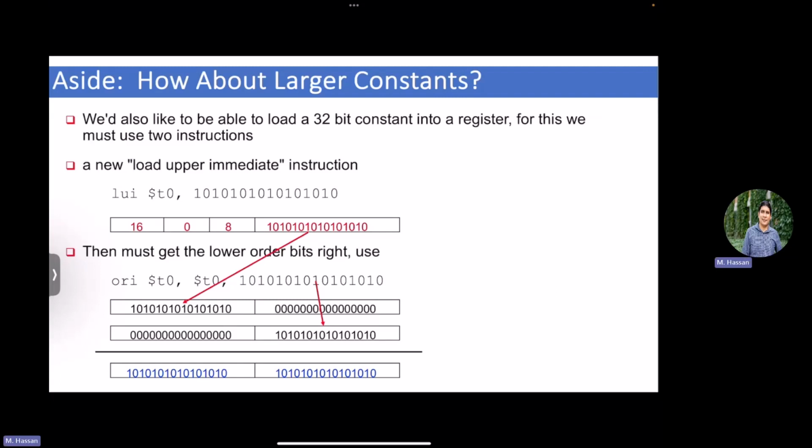So if I want to add or multiply a constant that is bigger than 16 bit, I can divide it into, let's say, 32 bit, for example. I can divide it into 16 and 16. The lower 16 would operate with the lower half of the register, and the upper 16 would operate with the upper half of the register, right? So you divided your operation into 2 halves, one for the lower half of the register and one for the upper half. Make sense or confusing?